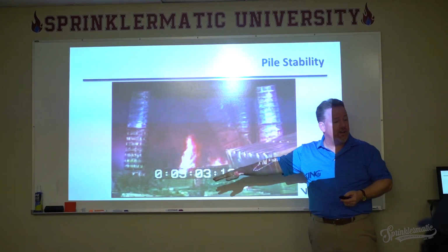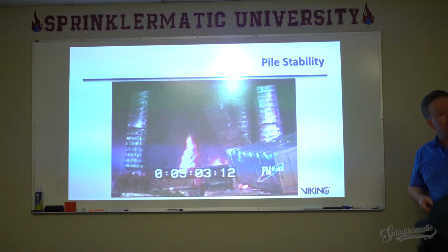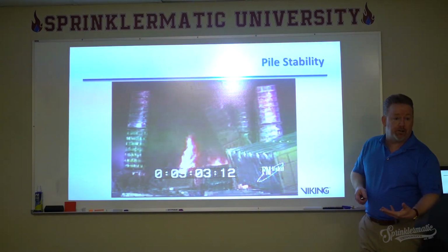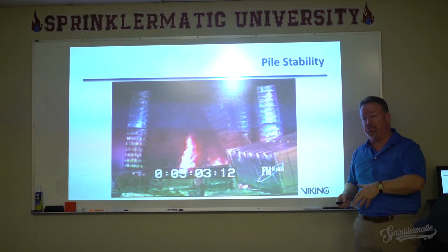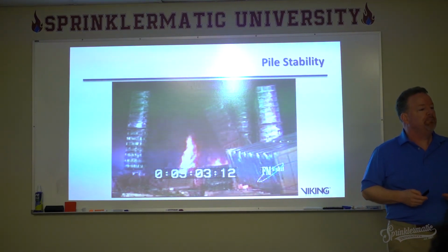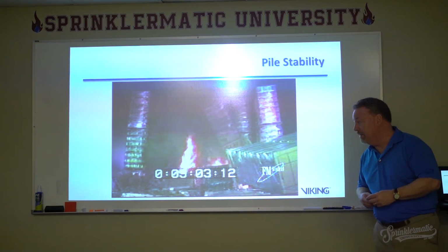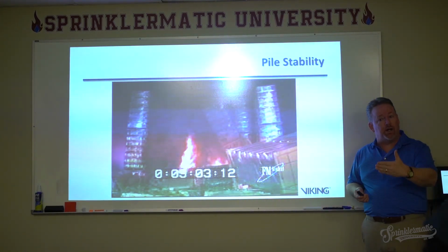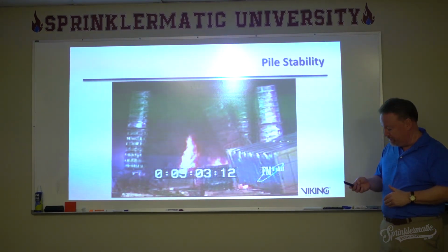If the piles are not stable and have a tendency to fall in on themselves, you have a smothering effect on the fire. It actually helps in fire control if you have an unstable pile, because everything will eventually fall in on itself and smother things. It's still a challenge to get to the base of the fire, but for the most part it's not as big a challenge as a stable pile. So the designer needs to take a look at that as well, and that's where wood pallets and reinforced plastic pallets come into play.